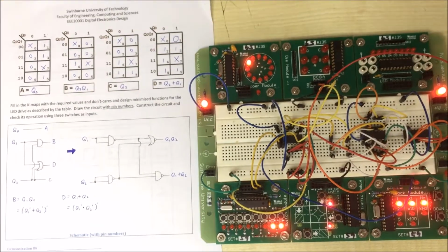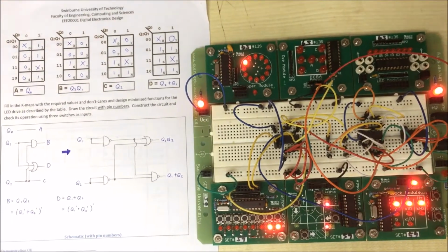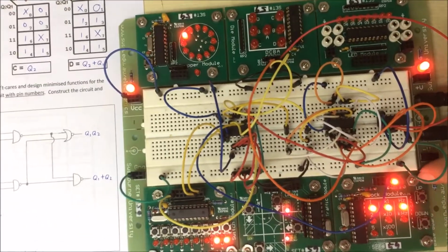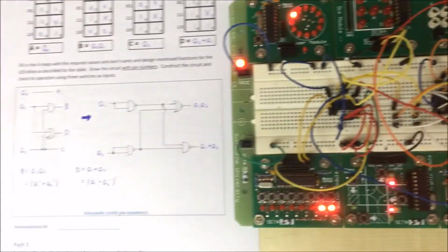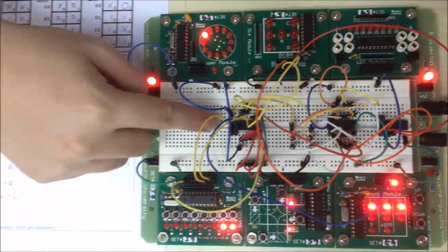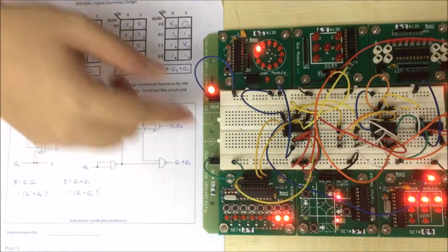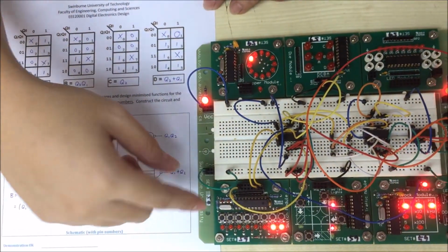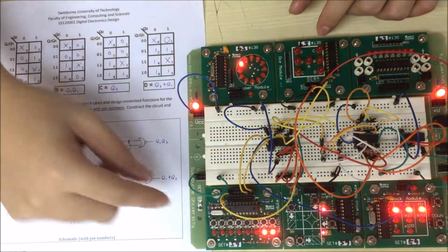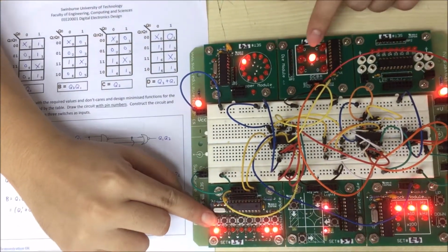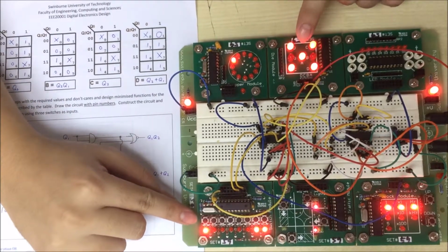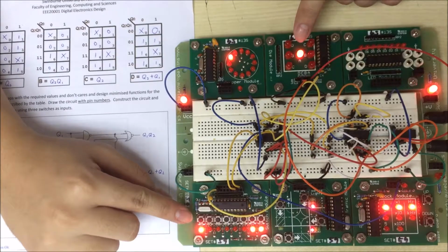For part 4 and part 5, I combine them together. For the clock, I first set it to 1 Hz, and then from the schematic diagram, we build a circuit. This is the NAND gate we use, and then the 4-bit counter. So when I open the counter to count from 1 to 6, it will show the die pattern for each. This is 1, 2, 3, 4, 5, and 6, and then it goes back to 1.